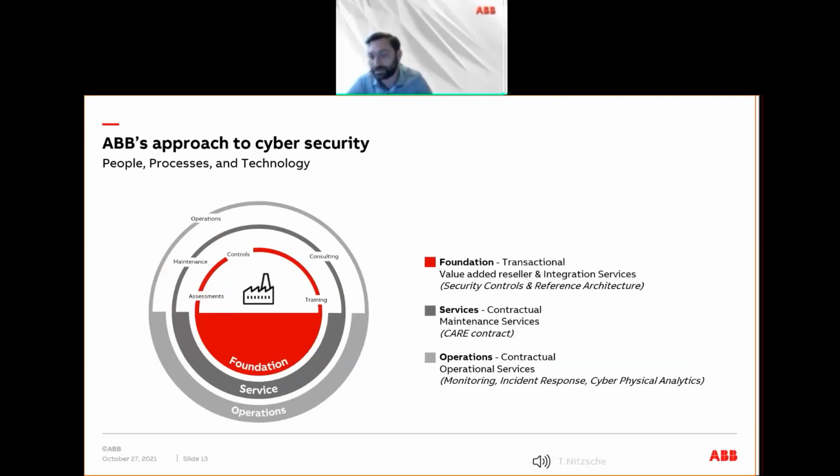And on the next topic, consulting, we will help you, for example, identify the right incident response plans or a disaster recovery plan, or we can help you tighten the role-based access control for the DCS system. Do we really need to have only three kinds of people, operators, engineers, and administrators, or is there a way to make it more granular in a DCS system? And there is. So things like that we can cover with consulting.